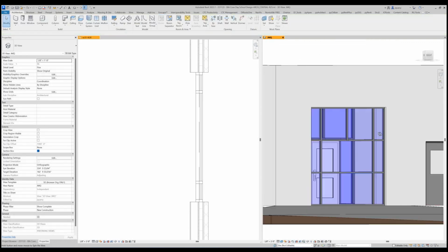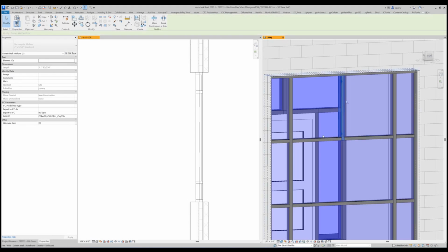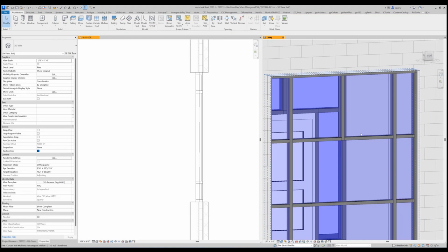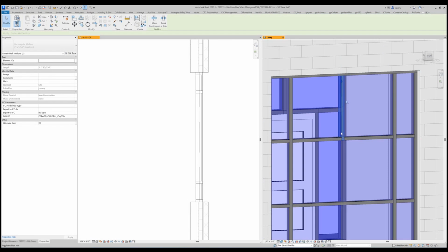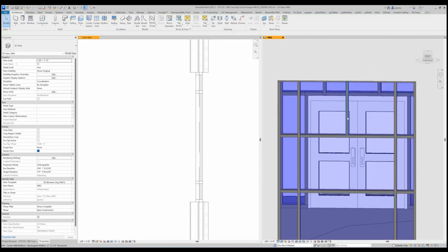The other thing that you'll notice here is it does matter which one of these is passing through the other. Most of the time your horizontals are through and your verticals stack on top of each one. Sometimes your curtain wall system will go all the way down the bottom and these are halfway because it all depends on the system. I typically don't worry about this real quick off the bat, but I know that this is going to be a transom, so I might as well go ahead and make it look that way.